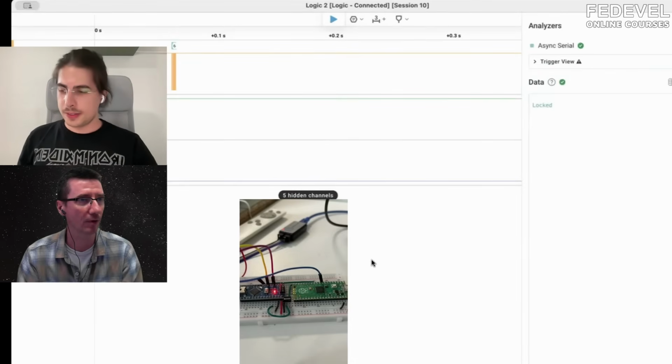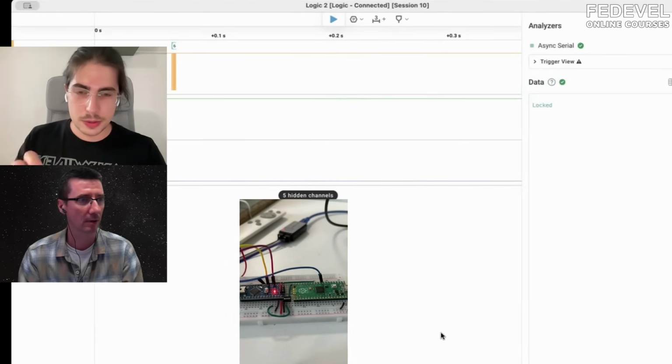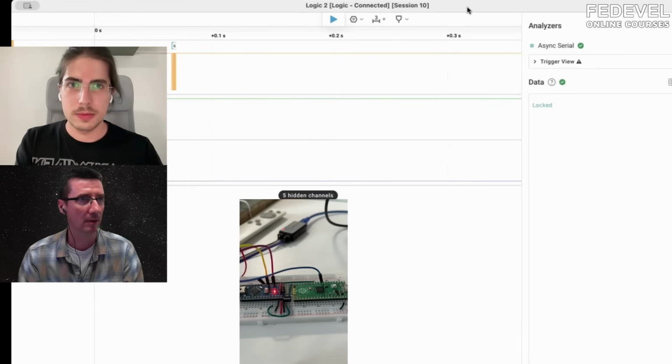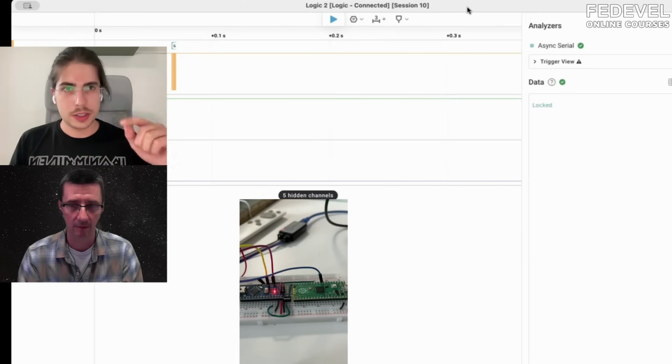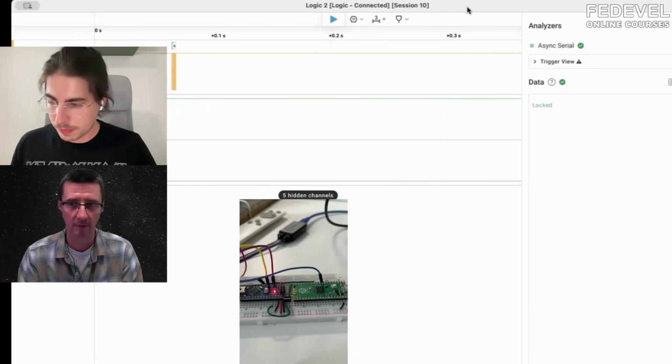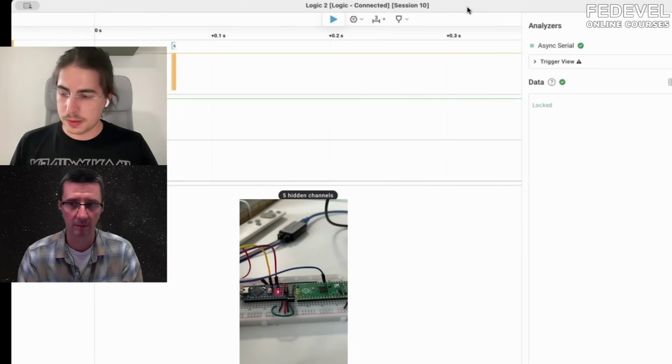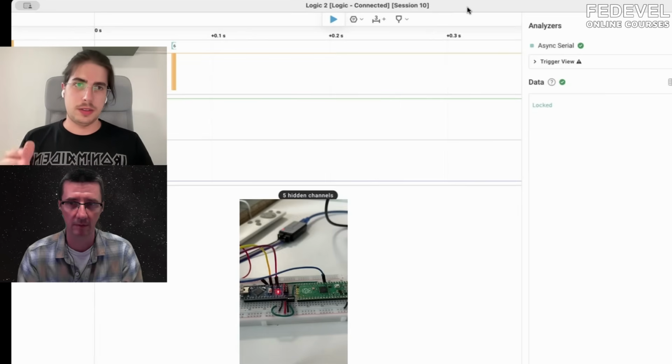Okay, a little bit more, because I still don't understand. Can we see all the code, for example? Can you show the code? Sure, or it's easier if I describe it. The code is just a loop counting from 0 to 255. And by injecting a small glitch in the core voltage of the chip, we can basically pause the execution for a few nanoseconds so that a few instructions don't get executed.